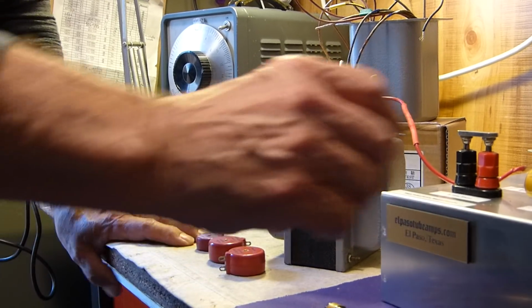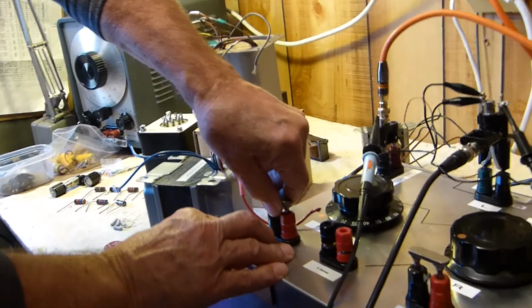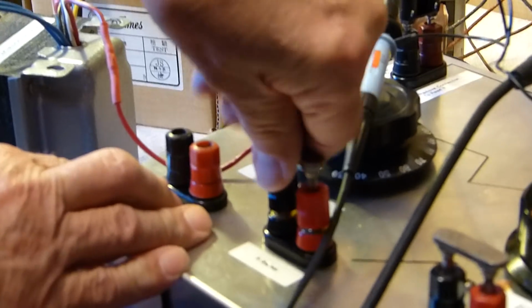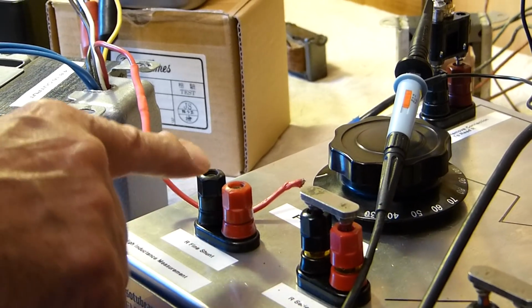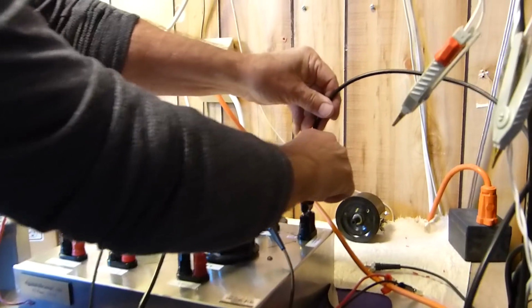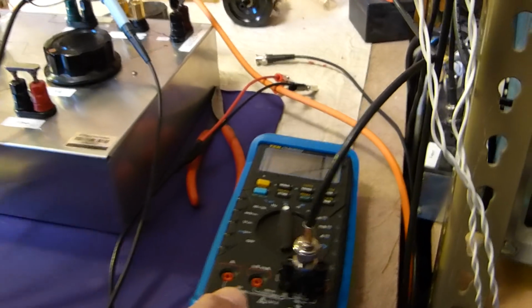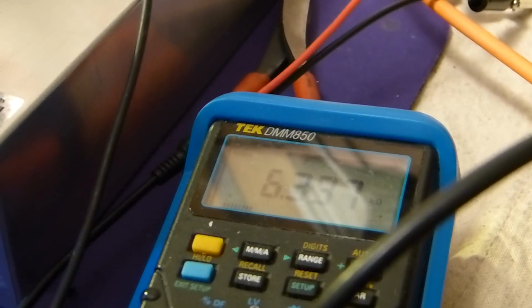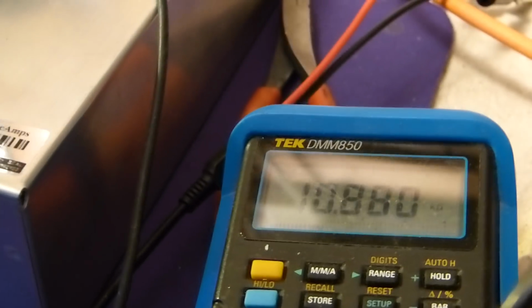Now, I'll show you one other thing here. Again, if you don't want to use these resistors, let's just take this one off. Now let's use our shorting bar to go over here to this one. Now I've shorted my R, so now this one is the one that's open, and I can dial in. What I have to do to dial in, though, is put my resistor here across the output. This is a really nice, accurate little meter, but then I can dial this in. Watch, I'll dial in 10K, 8, 9. Whoops, went a little bit past it.